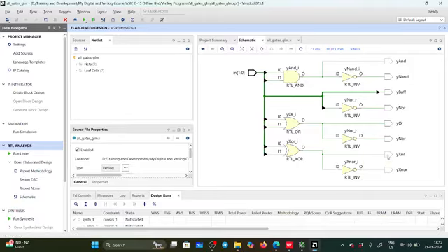This is the XOR gate, and the XOR gate followed by this inverter is XNOR. So depending on my code, this compiler, the Vivado tool, is converting it into hardware, that is a netlist. This is nothing but a gate level netlist, or we can call it a schematic. Is it fine? This is gate level modeling.